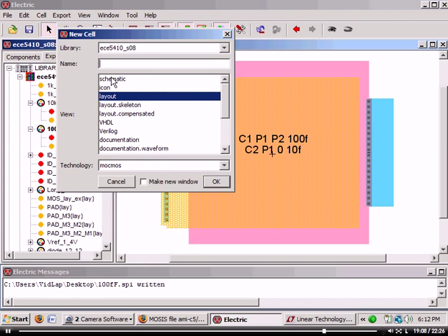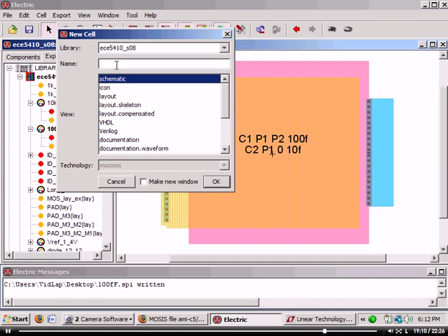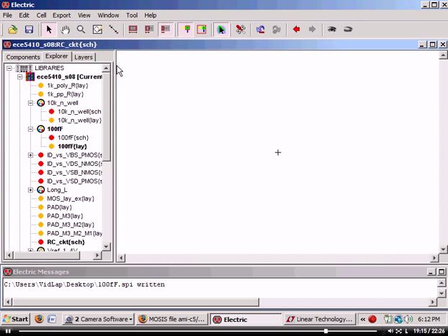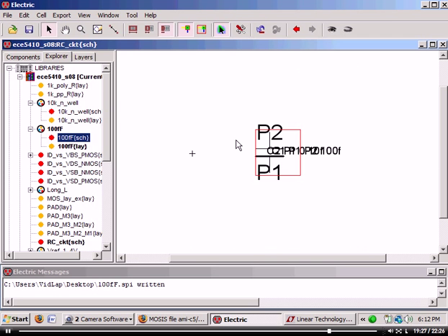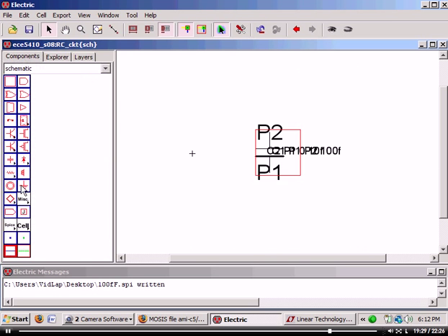If I go through here and do an RC circuit, and then drag my layout in here, Control J a few times, and then show, oops, a couple more, because I want that, fit, expand, go show my ground, making connection.